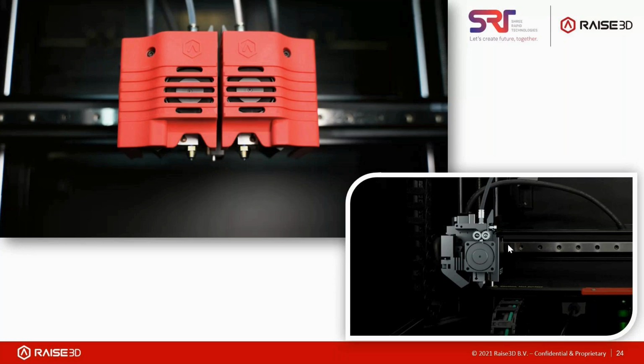It has a dual direct drive extrusion system. The gears are made of high hardness steel and are heat treated for higher wear resistance. The extruder also has a custom gear tooth profile, so the filament is firmly held in place to ensure that it does not slip when extruding, and it gives enough force to ensure stability of printing.